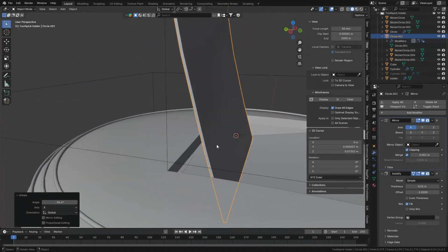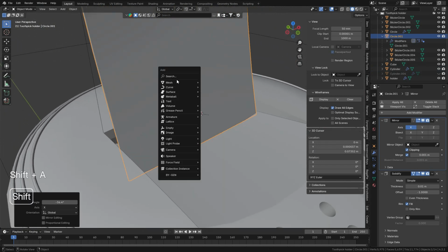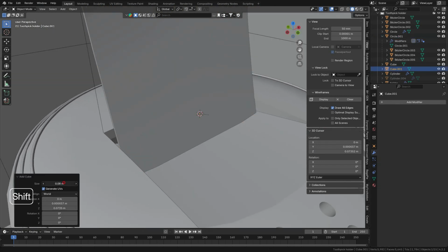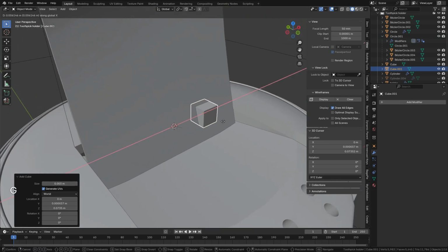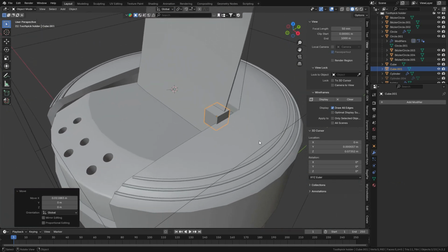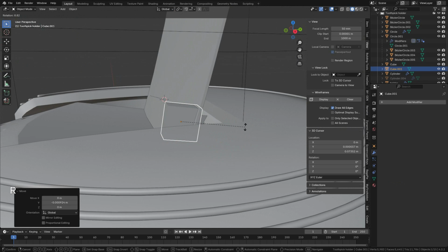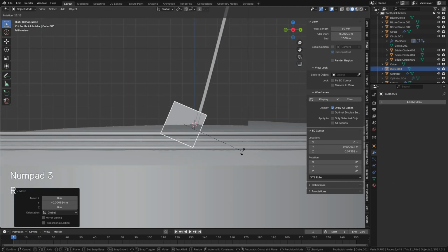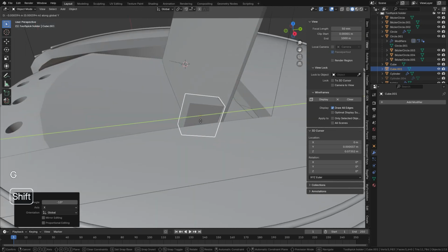And what you can do is we'll create some sort of hinge. I'll do it with a small cube. So go to add mesh cube, scale this down from here. Think about that big should be okay. Move it here. Scale X. Move it here. Grab Y. Then kind of just rotate it. Go to side view. Then rotate it on the X axis. Somewhere like this should be okay. Okay. So just move it here a bit. Then G Y.